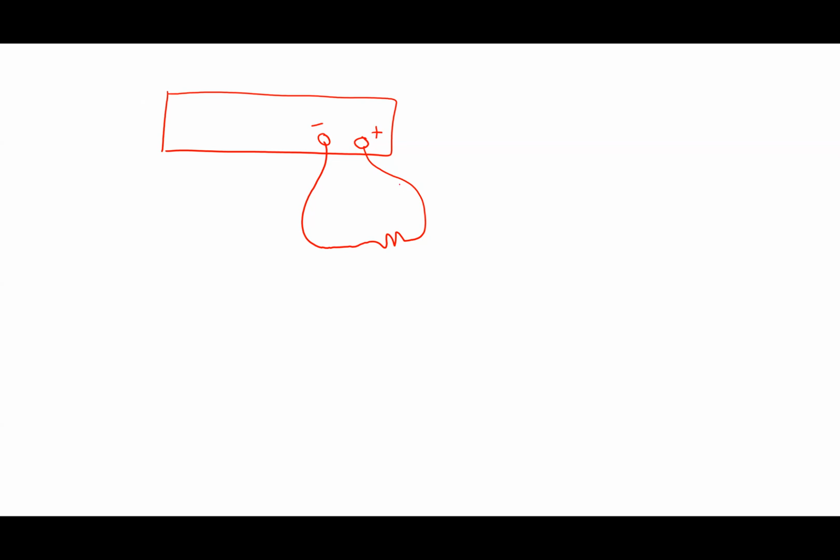Yeah, well, why doesn't it go here? Why don't the charges move here through the air? Well, in other words, the conductivity of this resistor is way less than that of the wire. I'll say the conductivity of that copper wire is much, much greater than the conductivity of air. There's a factor of 10 to the 12 difference between copper and air. So as a result, the charges all move through the wire.